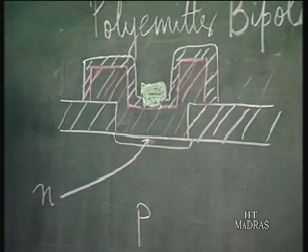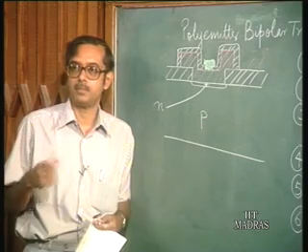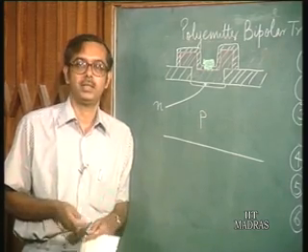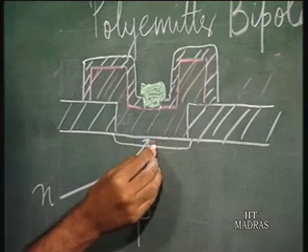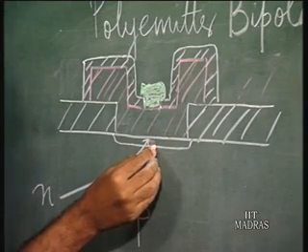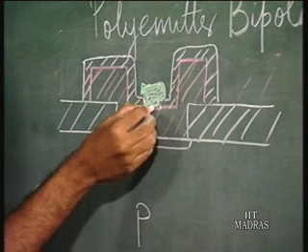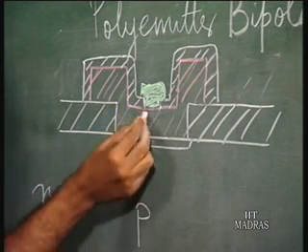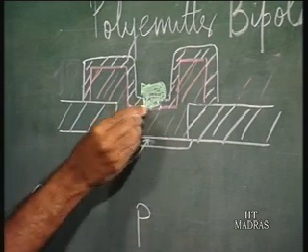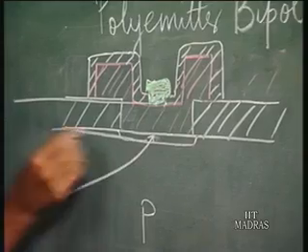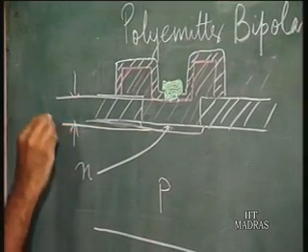So, as I said, for calculation of beta, the total emitter thickness is going to be taken as this thickness inside the silicon of the N region. The N region starts from the junction here right up to the metal contact here. Okay. So, the total emitter thickness WE is actually this. This is WE.